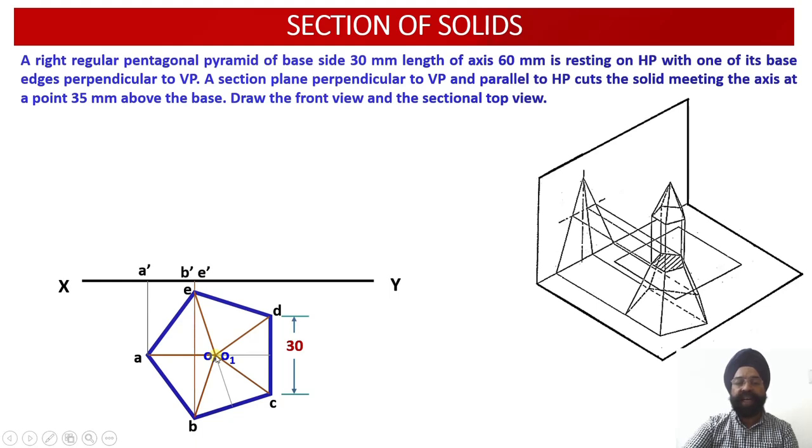And before we start drawing the front view, you see many students, they often make this mistake that they are going to join these two ends, that is these two corners over there, B and E, and they will be just lifting this up and mark the axis height over there. No, the axis will be lying always, as I have been discussing this number of times.